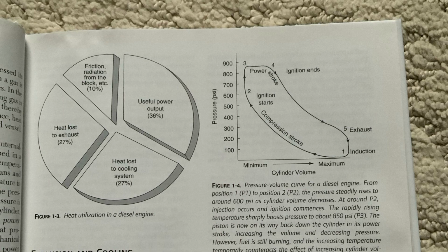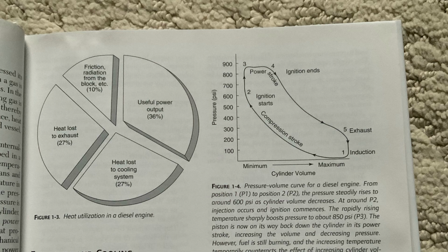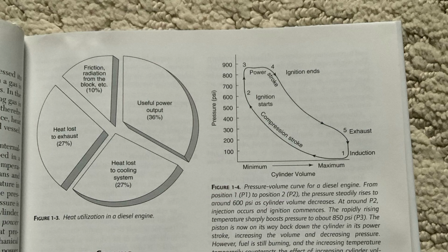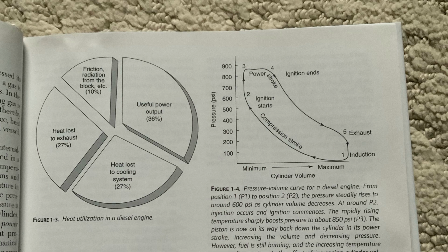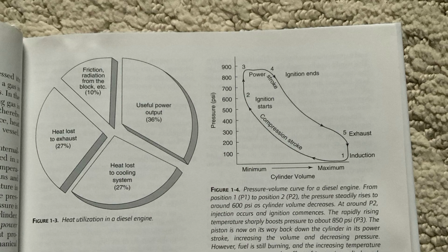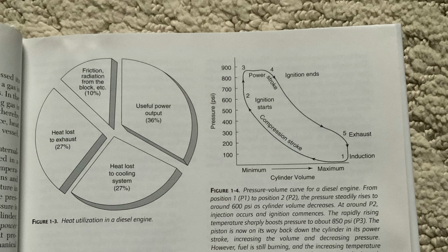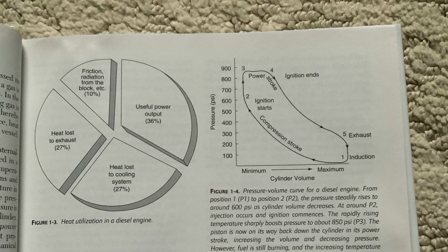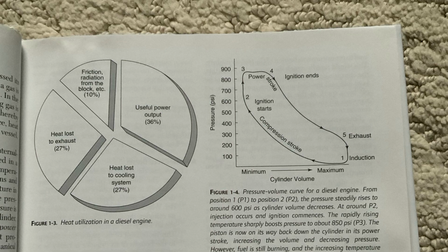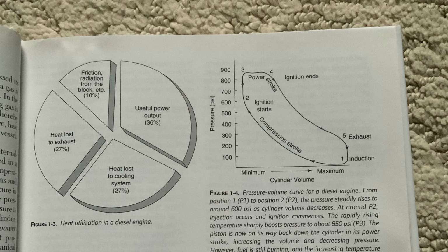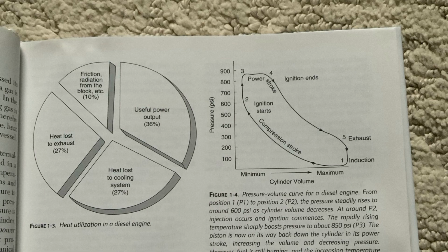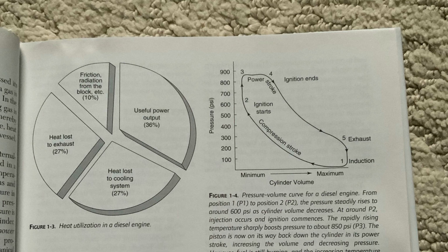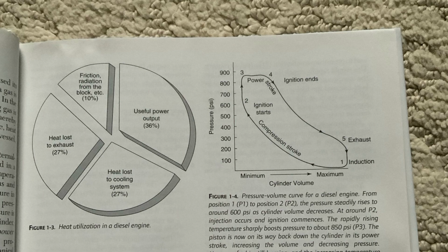Types of diesels. Diesel engines can be 4-cycle or 2-cycle. The differences will become clear in a moment. Let us first look at a 4-cycle engine. A 4-cycle diesel. 1. Imagine the piston is at the top of its cylinder. The inlet valve opens as the piston descends to the bottom of its cylinder. The descending piston draws air into the cylinder.